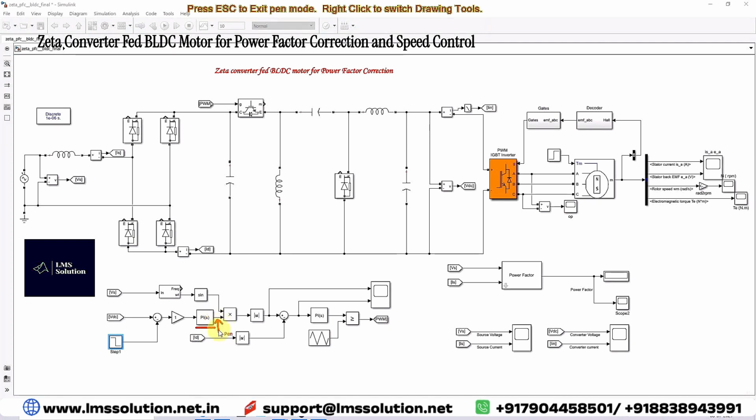This reference current magnitude is multiplied with a sinusoidal waveform. Here we get a sinusoidal waveform with an amplitude of 1, which is generated based upon the source voltage. That means we measure the AC source voltage, which is processed via a PLL to provide omega t. That omega t is processed via a sine block, and here you will get the sinusoidal wave. After that, the sinusoidal waveform is multiplied with the controlled output of the PI controller, that means the current reference magnitude. Here you will get a sinusoidal current reference.